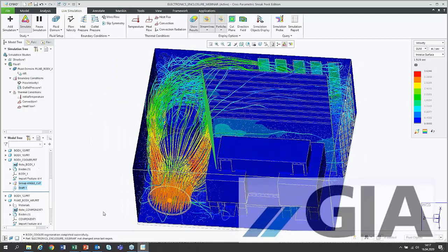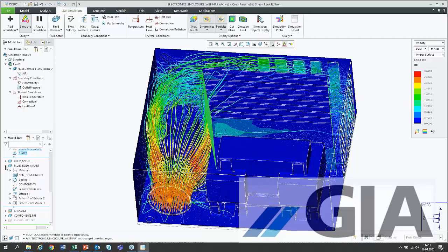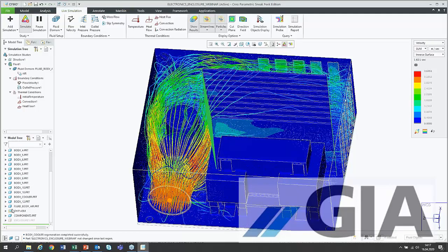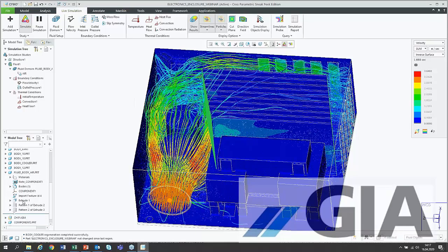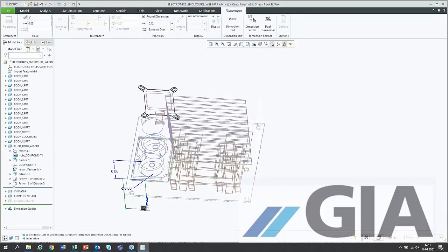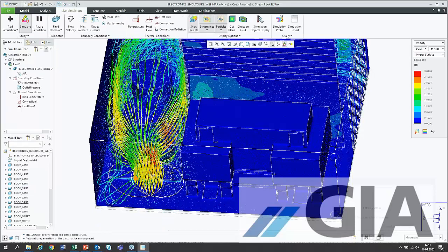And now I'd like to move the inlet here. This construction was built in a slightly strange way. I have to change the fluid body to change the inlet, so I'm going here to that extrude. I'm just changing the dimension from 0.5 meters to 0.75 meters. I have to hit regenerate in order to see the changed dimension.